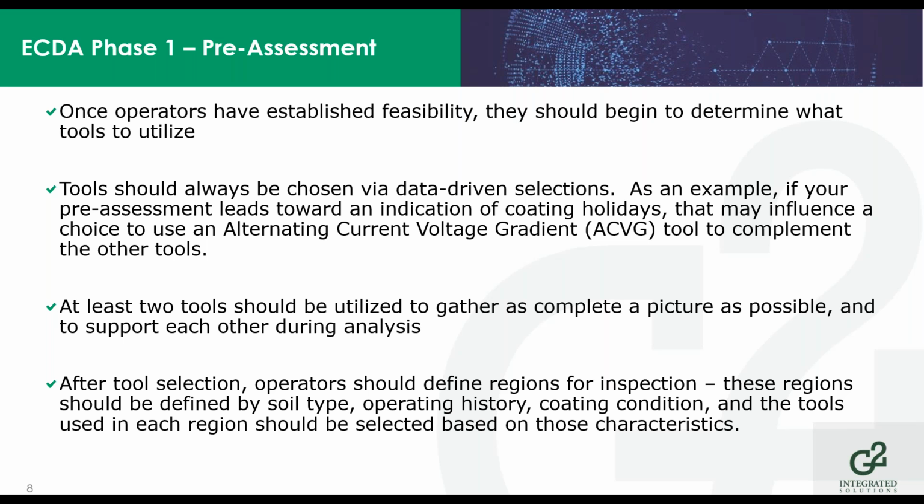NACE SP 0502 does require that you use at least two tools for all locations and regions. Tools selected should be complementary to each other in order to develop as complete a picture as possible.